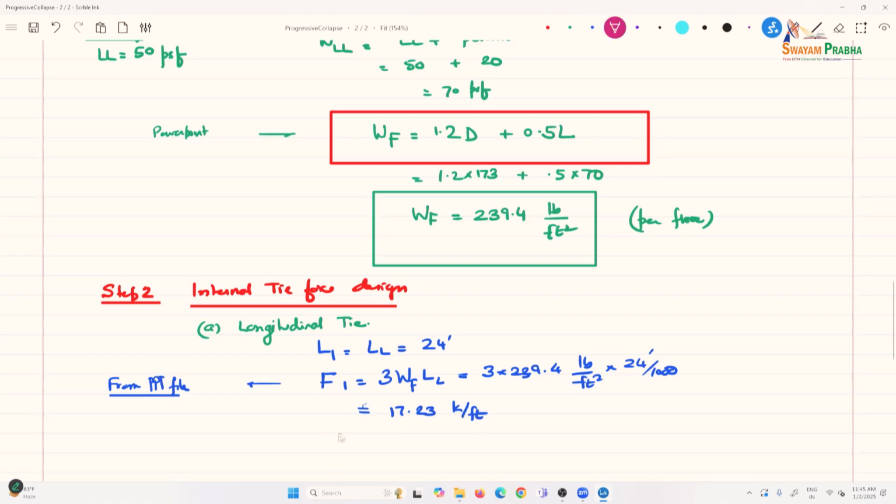And so, the steel area required, this is additional steel, it goes as F is equal to AS, assuming the steel yields at that force, which in catenary action it will, multiplied by the overstrength factor.